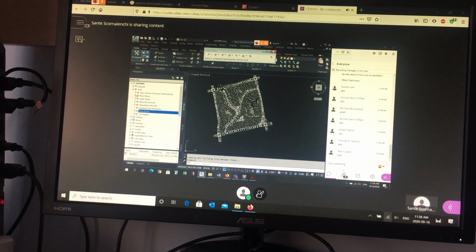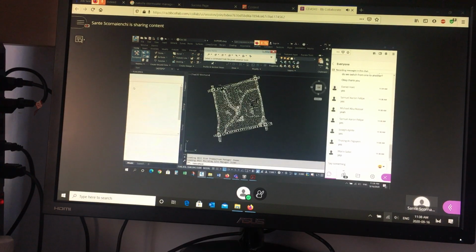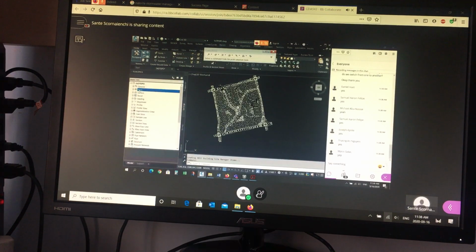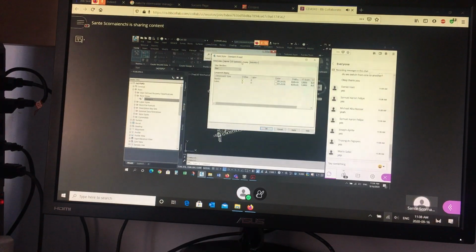So if you go to point styles, let me start that from scratch again. Bring up your tool space, go to the Settings tab, and go to point styles, and you'll see the standard style. Right click, make a copy. Always start with the standard style. Go to the Information tab, change the name. This one's called Point.